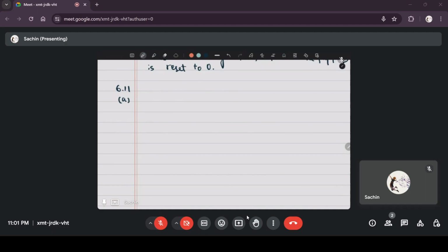So in the first part, if you connect the normal outputs, we get a down counter that counts down from 1111 to 0000 and starts back at 1111.